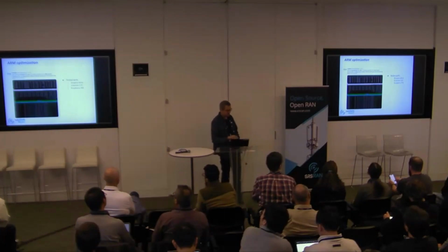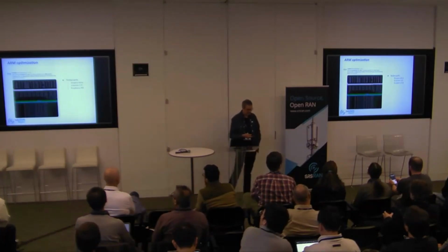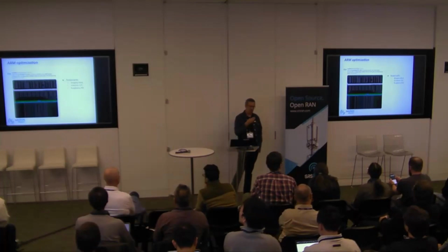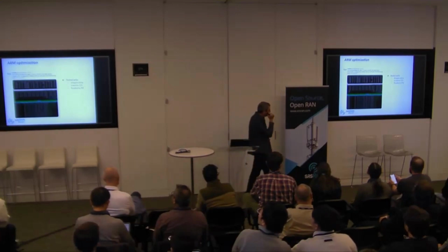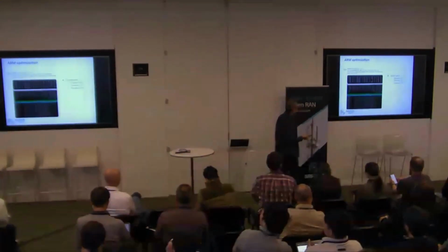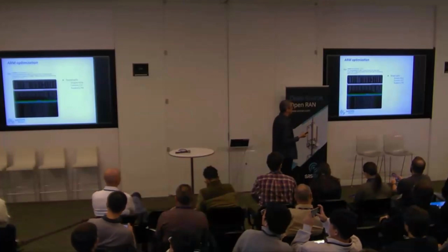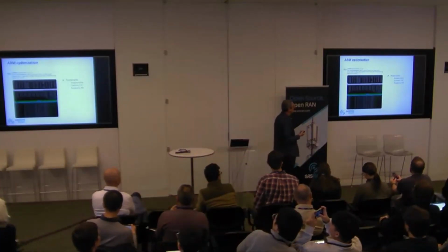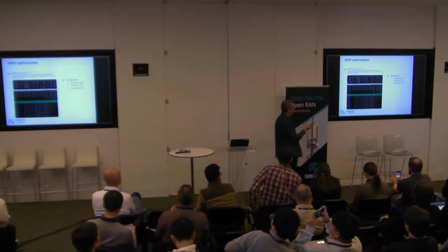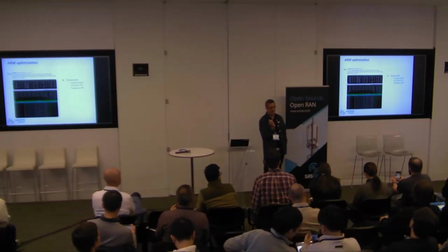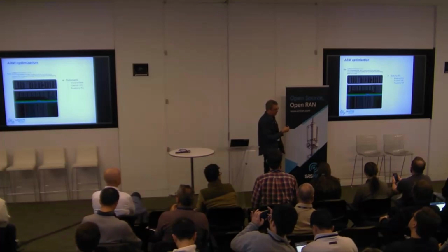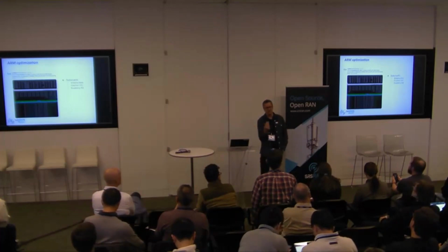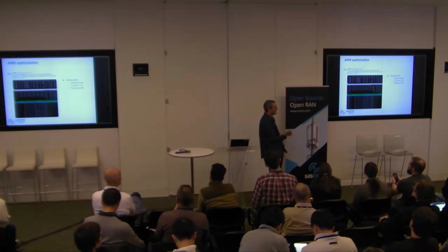On ARM optimization, we also did a lot of work. We optimized some of the code on the DSP, but also on the fronthaul interface. This is an example of a test doing 600 megabits. So this is 100 MHz 2x2 cell using an Ampere Ultra, which I think has like 80 very small ARM cores. And with these kind of platforms, when you say 80 cores, you think, oh, that's an impressive amount of processing, but it's very hard to distribute this processing efficiently.